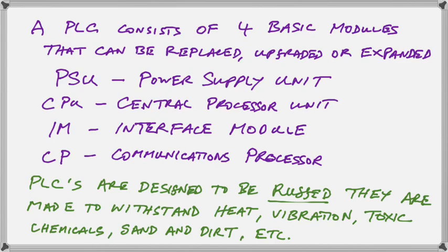But if you're using this PLC in a factory situation along with other PLCs on an assembly line, then chances are your communications processor will interface the microprocessor of your PLC to either a copper wire line or a fiber optic cable. So those are your options for use of your PLC with communications.